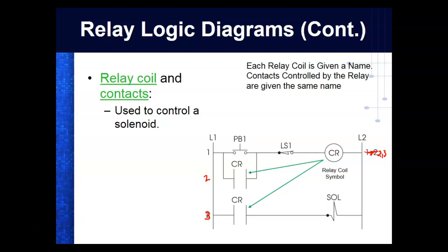So the book, like I said, in motor control or in relay logic, we number lines. And every line that lines up gets the same number. So if I was to come over here and put a light in parallel with this one, since it lines up, it does not get a new number. It gets the same number. So draftsmen really make sure they line these things up as many as they possibly can, so that they don't have to use a bunch of line numbers.